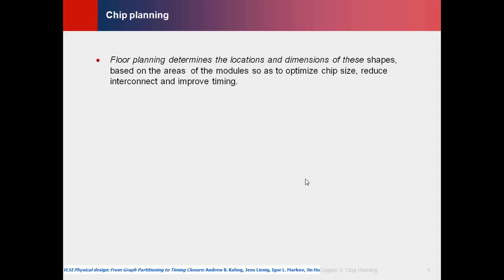So this is what I would define as floor planning. Floor planning determines the locations and the dimensions of these shapes based on the area of the module so as to optimize chip size, reduce interconnect, and improve timing.